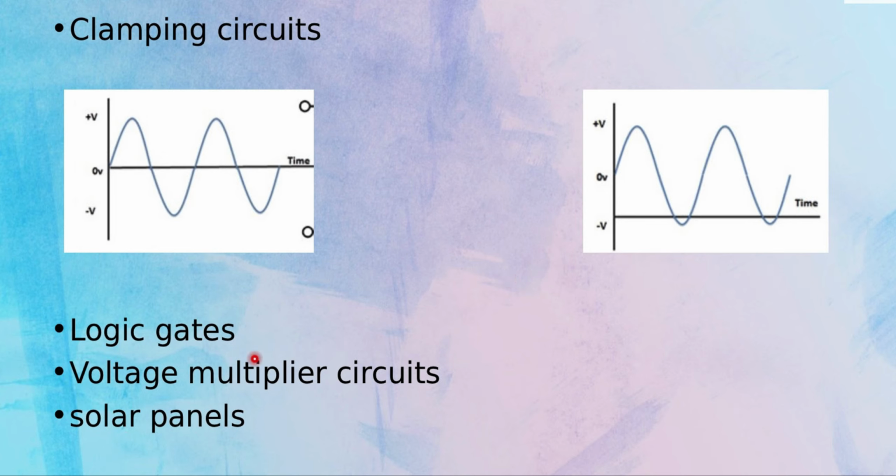Finally, they are also used in solar panels. The diodes which are used for protection of solar panels are called bypass diodes. Now, if the solar panel is faulty or damaged or shaded by fallen leaves, snow or any other obstructions, then the overall output power decreases and hotspot damage arises because the current of the rest of the cells must flow through this faulty or shaded cell, causing overheating.